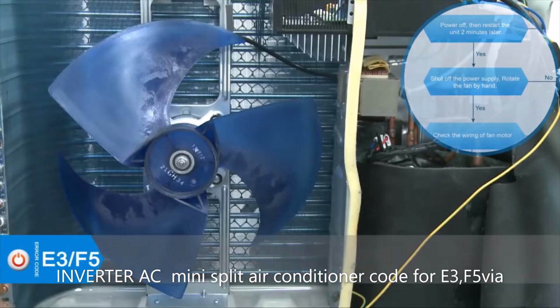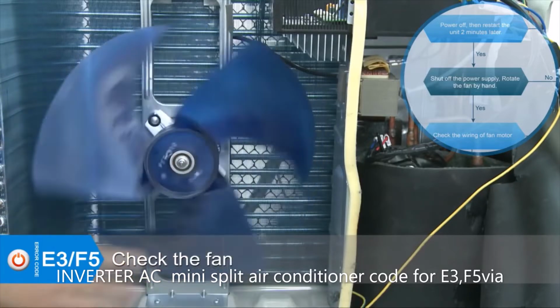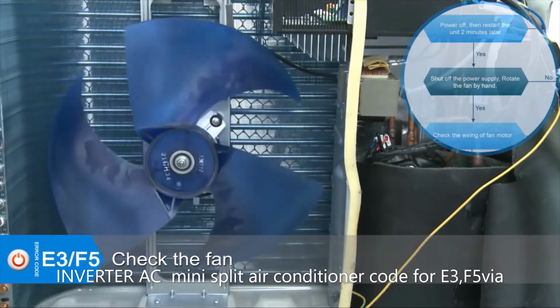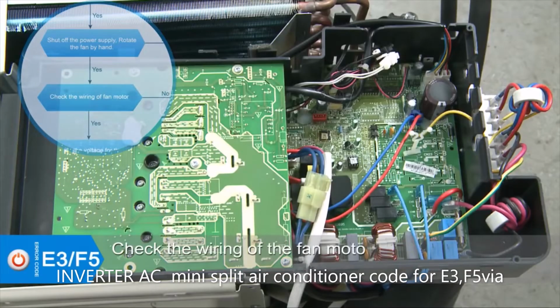If the error still exists, shut the power off, then check the fan. Rotate the fan by hand. Check whether the fan is blocked or rotating normally, and whether the screws which fix the fan have been tightened enough. If the fan is normal, check the wiring of the fan motor according to the wiring diagram.